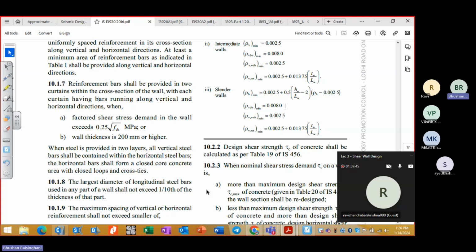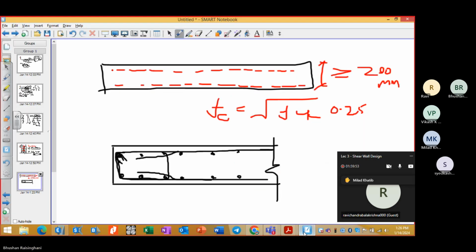So keeping a boundary element, how it helps that your congestion in the... Yes sir, you can speak. Sir, concerning the stirrups, we will discuss it in the future. There is some recommendation in the code concerning the tie, the angle and the length of the end of the stirrups. It should be at least 10 phi with certain distance inside the beam. Otherwise, it will not be effective.